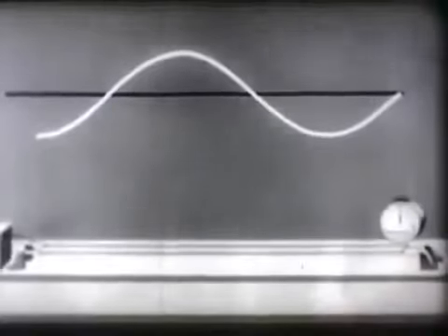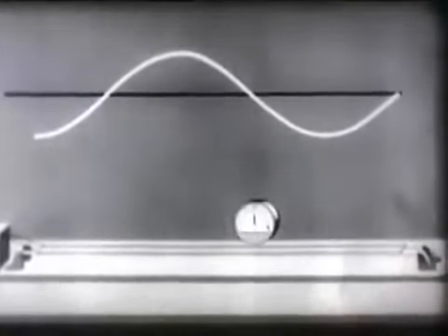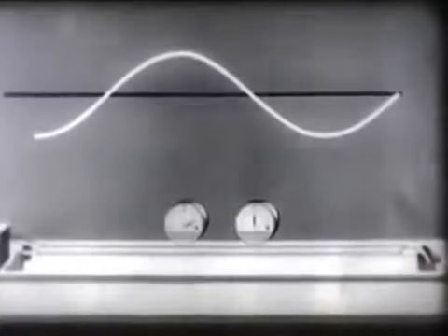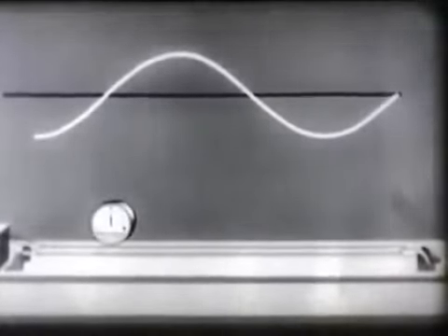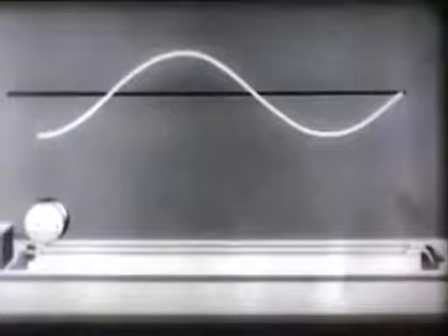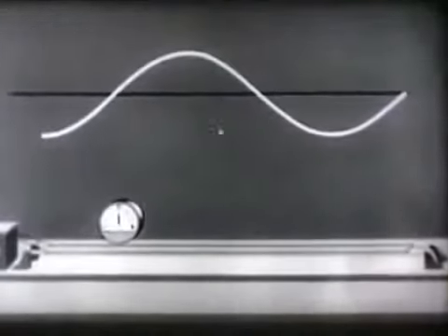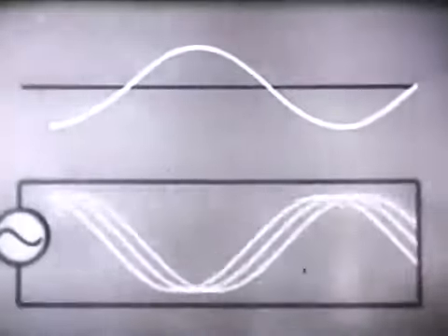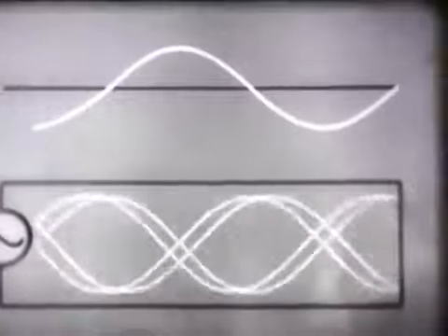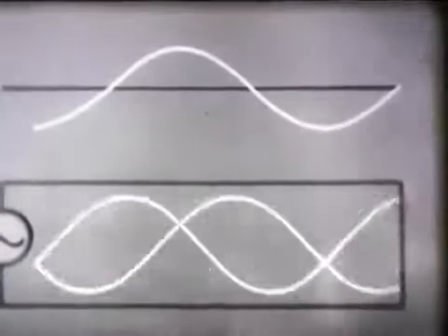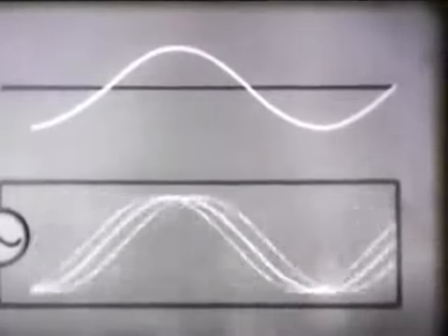If a zero-center reading voltmeter could be designed to read this electrical phenomena, it would give the same indication as the voltage plot, the same indication as a fluorescent lamp, which reacts to voltage. The rise and fall of voltage and current follows the standing wave. Remember, this standing wave is not a physical thing, but rather the resultant values of the combined incident and reflected waves at any point along the line.